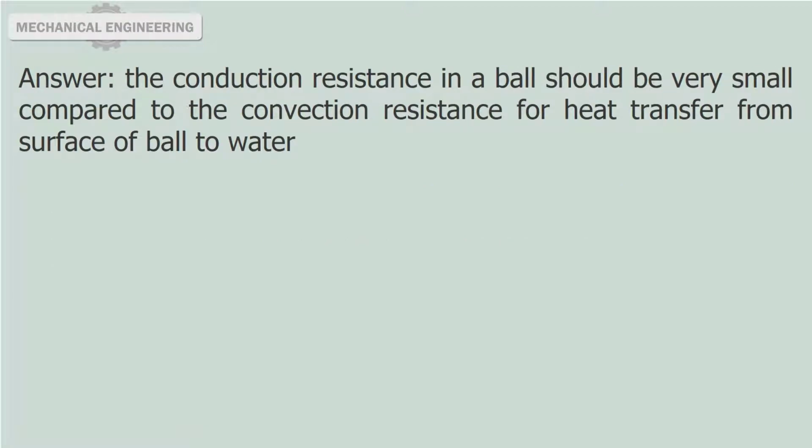Answer: the conduction resistance in a ball should be very small compared to the convection resistance for heat transfer from surface of ball to water.